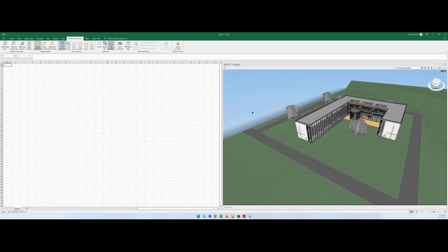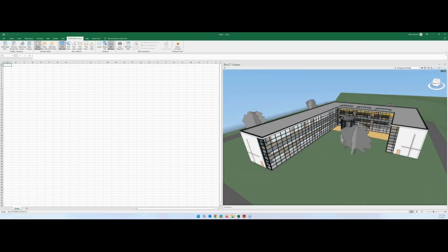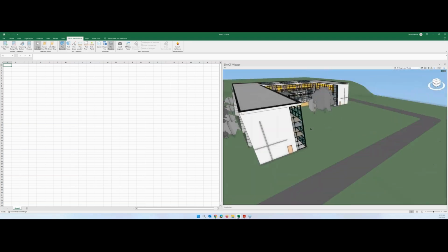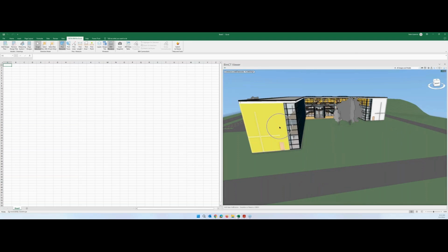Okay, so the idea is not seeing the Revit file, but the idea is to start understanding the drawing. First of all, when you select any object, the system also provides properties here. So this is the ID of the element, the label, the type is exterior walls, and these are all the technical parameters and measurements which we are receiving from the design file. So you are able to access all the total area, height, length, thickness, gross amount, net amount of the area.